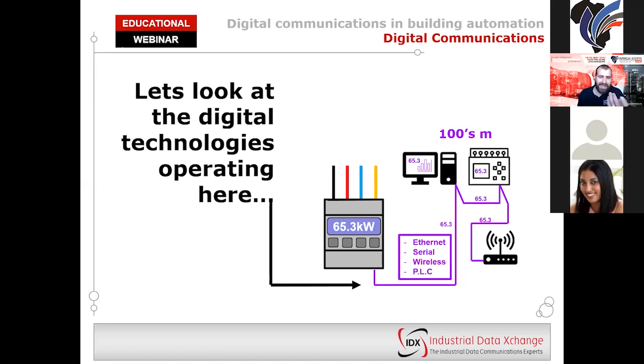So within a LAN environment, we can also mention isolated versus integrated networks. An isolated network is typically only a few devices linked together that directly require one another to perform a task. Isolated networks are not linked to a larger building-based network. It might only span a single room, for example. An example might be an occupancy sensor that is linked to a light relay that is linked to maybe a room-specific HVAC controller, so heating, ventilation, and cooling.